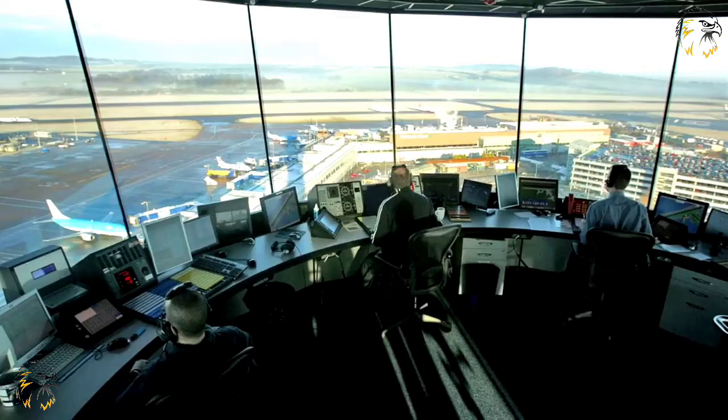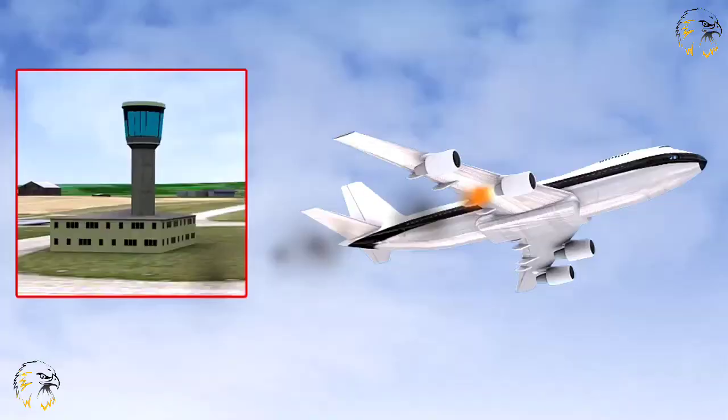Air traffic controllers will not issue any clearance or instruction to execute a manoeuvre that would reduce spacing below the applicable separation minima. Should it be the case that an aircraft cannot maintain the standard separation minima required for normal navigation, usually in cases of emergency or unlawful interference, then a composite separation may be applied, where altitude and track separation of not less than half that specified in the normal standard is applied.